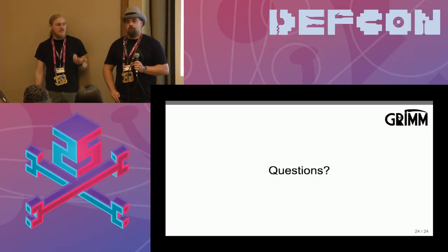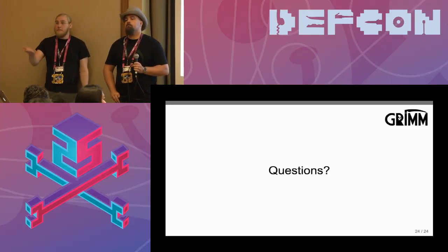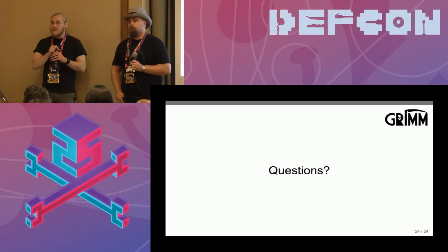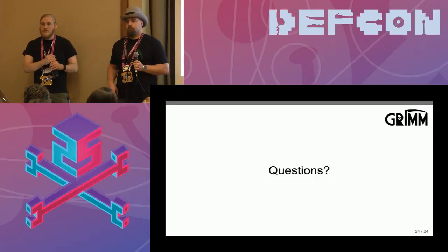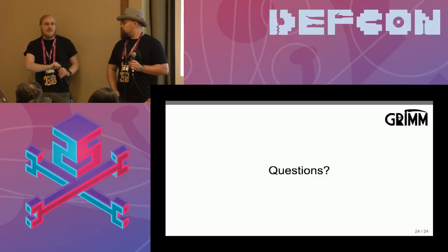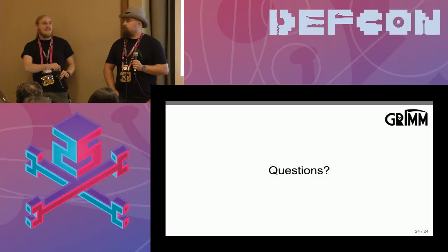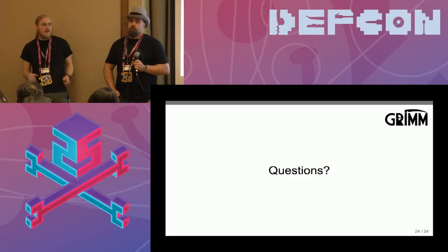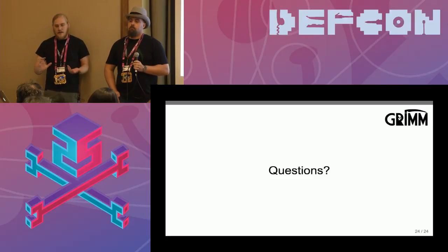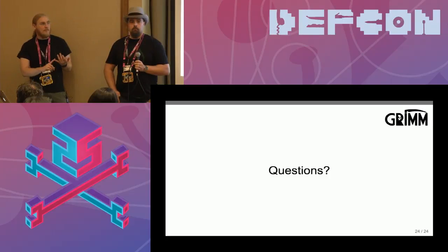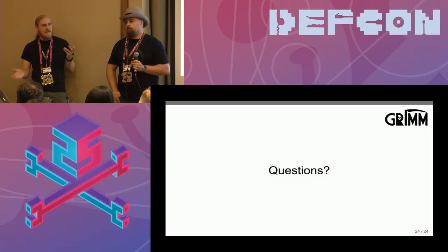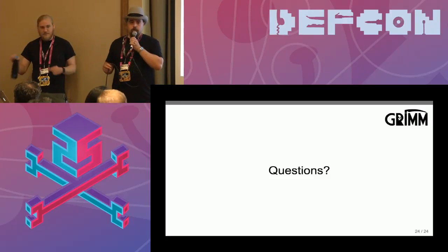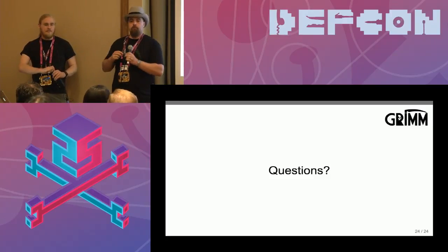There's no question what node something came from. Also, CAN is coming out with more security functionality than the existing legacy CAN. CAN-FD is a protocol which finally finished standardization this year, I think. It's much like CAN, and somewhat compatible with traditional CAN devices on the same bus. It expands the data payload to 64 bytes instead of 8, so you can fit a lot more in a message. It's also 8 times faster.